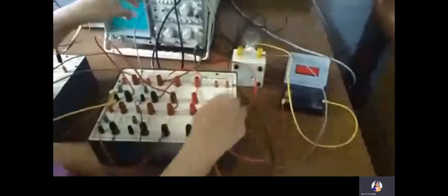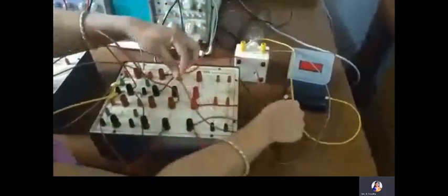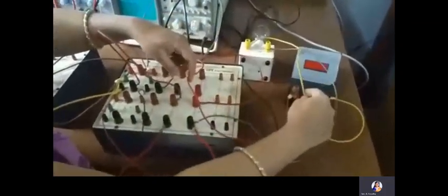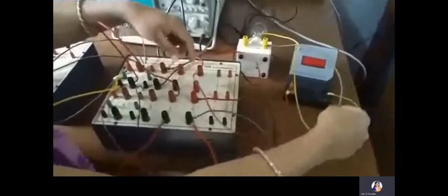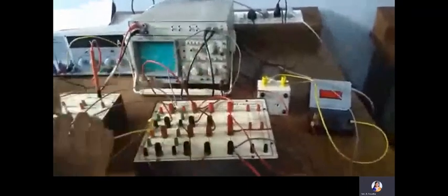Now, from the T1, T3 cathode connection, the wire is going to ammeter positive. From ammeter negative, it's going to the load. From the load, it's going back to the diode, diode anode junction. In the manual's circuit diagram, a 1 ohm resistance is shown. You can neglect it. First, we are conducting the experiment with R load. Then we will be performing it for RL load.